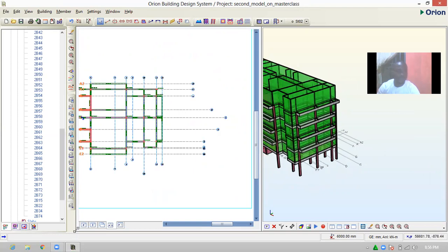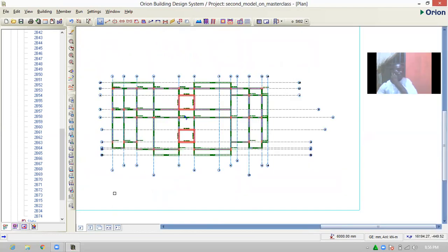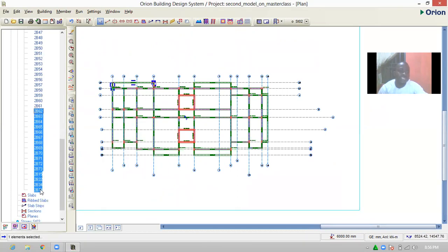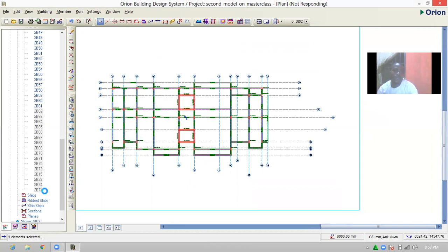All right. So now, having done this, we stopped at beam 61. So when I copy the beam wall load, any beam from 61 downwards is the one I added new. So I'll go to 62. I will hold it and select the last one. So it will select the newly added cantilever beams. I'll say Control V. Yes. It will paste the beam wall load on the newly added beams.